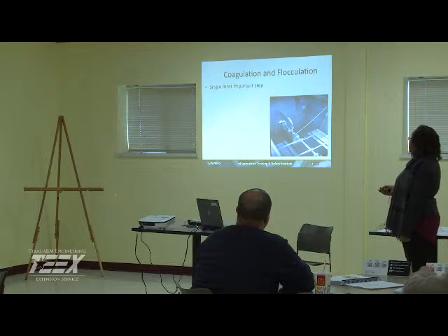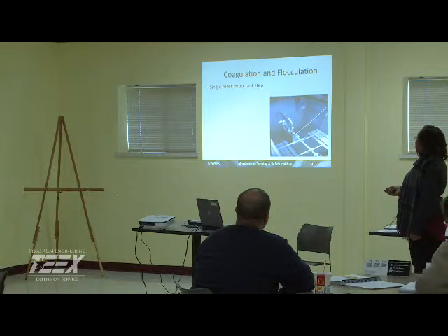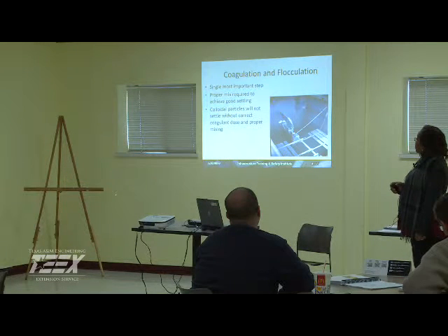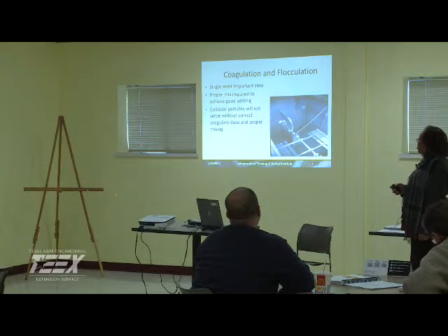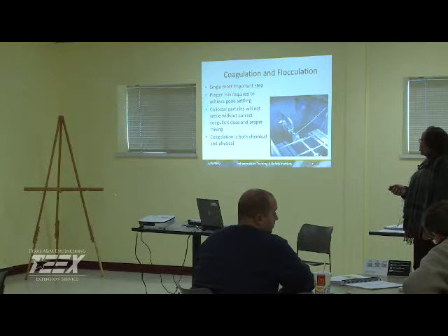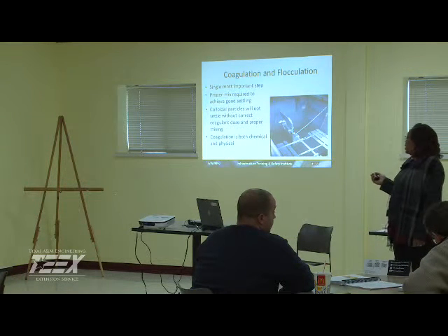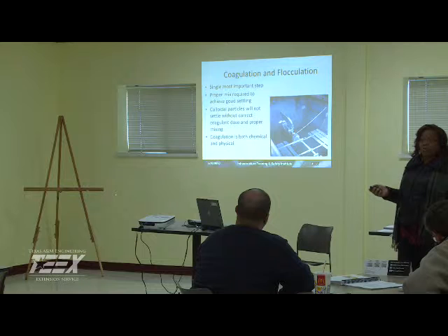So this is one of the single most important steps, this process of coagulation and flocculation. Proper mix is required to achieve good settling. Colloidal particles will not settle without correct coagulant dosage and proper mixing. So again, coagulation is both a physical as well as a chemical reaction that's occurring. You've got to have the mixing.